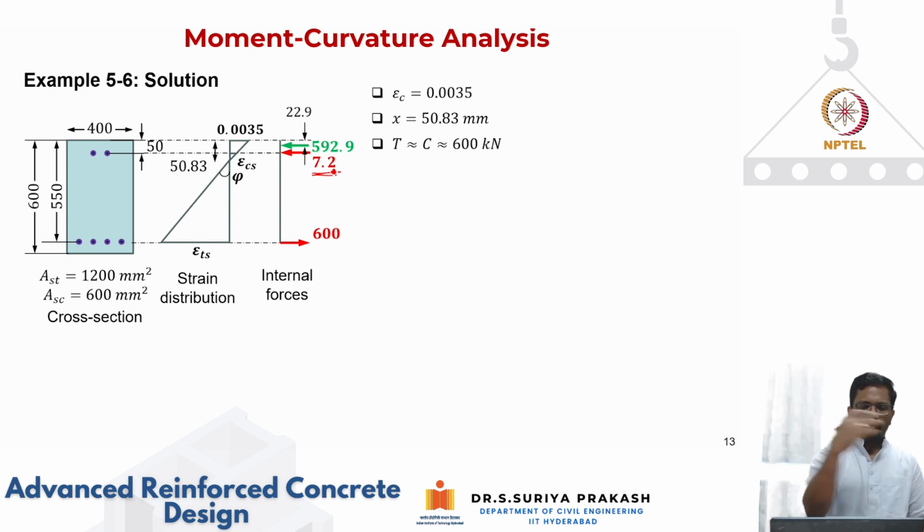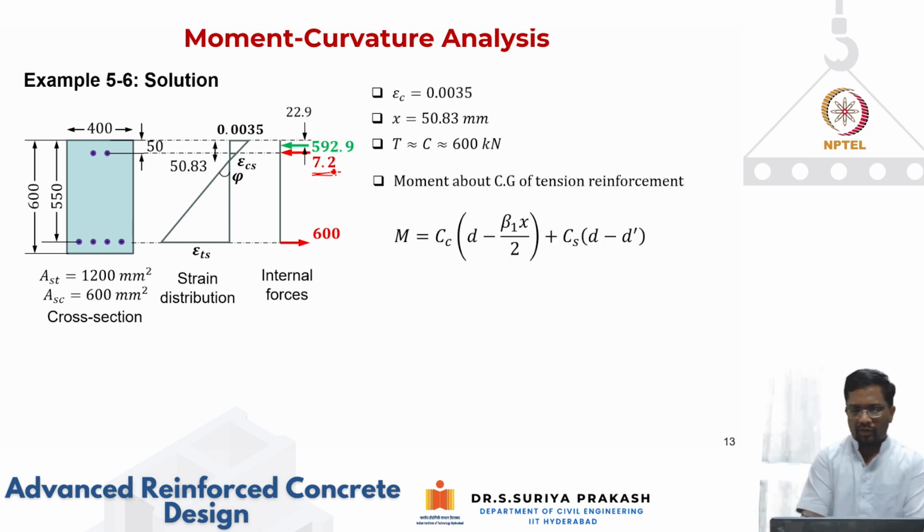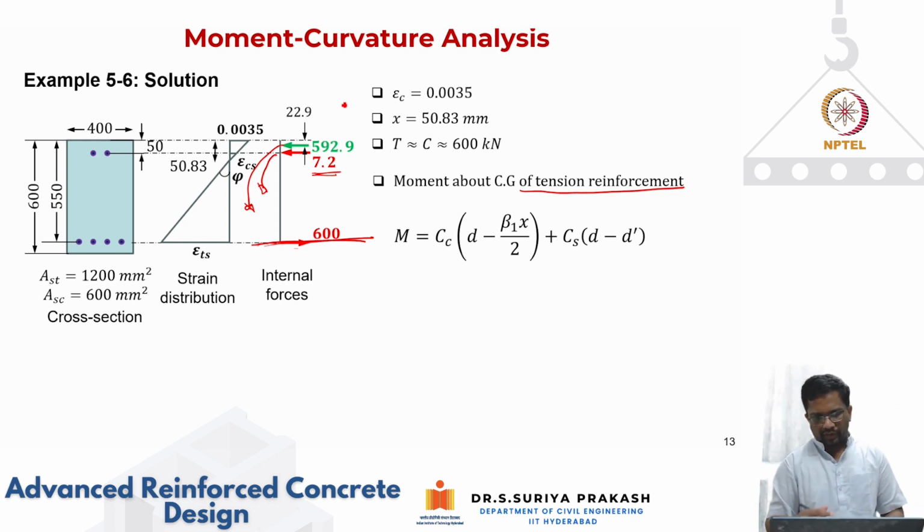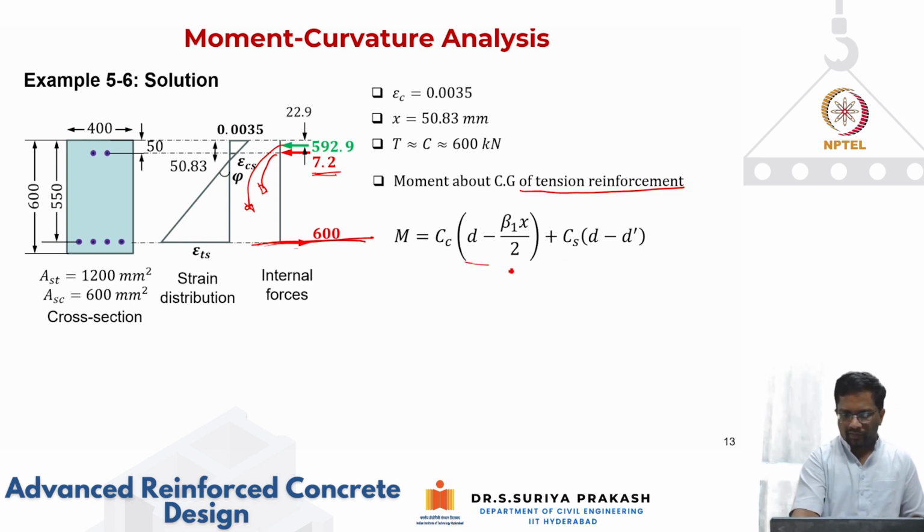It is in compression, so it is acting from right to left. Tension force is acting left to right. This is the convention that we have taken. So when you take moment about this point, this is going to act like this. This is also going to act like this according to their position, right? And these are their lever arm, like we have discussed previously.